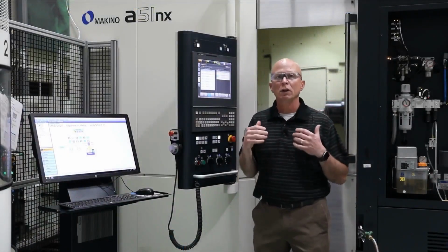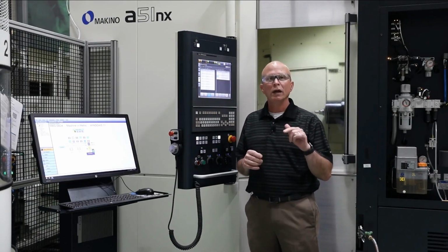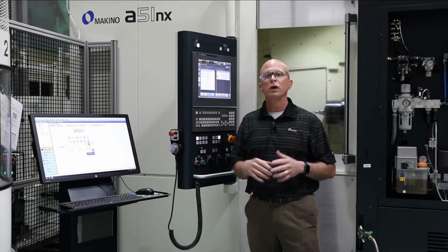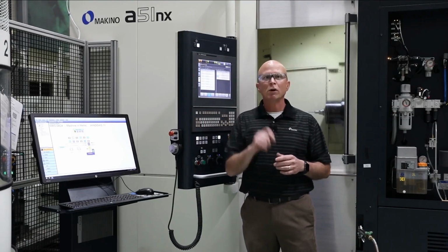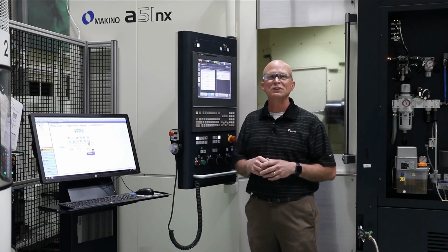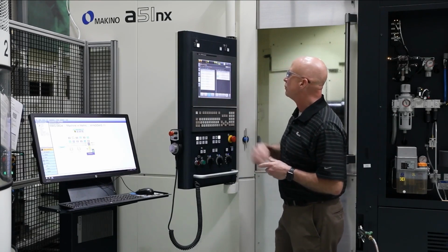And if you're tapping a lot of holes in your cycle, you're going to really implement and get that savings in that cycle time, especially over the course of your production run. So that 200% FANUC parameter change, 200% retraction, is going to get you where you need to be. So let's look at our next demonstration here.